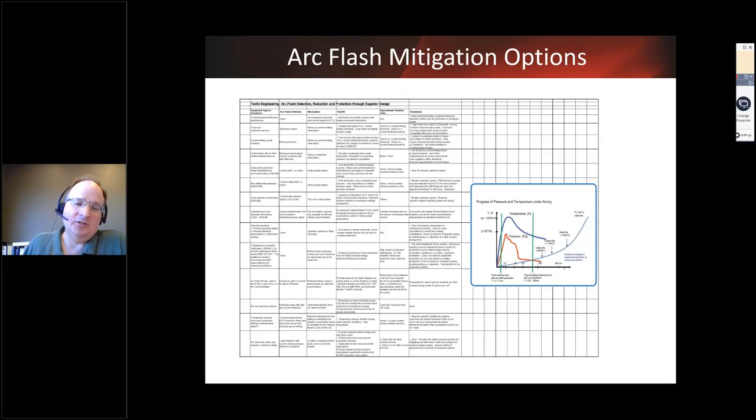It's not the purpose of this presentation to talk about maintenance switches, but I will tell you that the reason we don't support them is we believe that protective device coordination exists in the National Electric Code for a reason. Overriding protective device coordination when you need it most, which is during energized maintenance for testing, troubleshooting, or calibration, when it is most likely that a fault or arc flash event will occur, is not a good idea. Furthermore, we've seen maintenance switches sometimes left in permanent on positions, overriding coordination. For anyone who is interested in a maintenance switch, we would strongly suggest you consider zone selective interlocking instead.